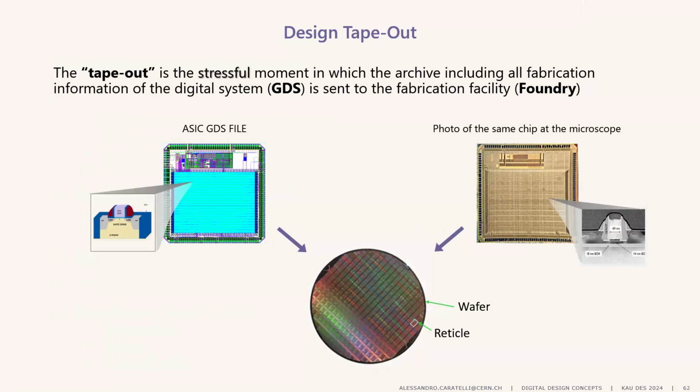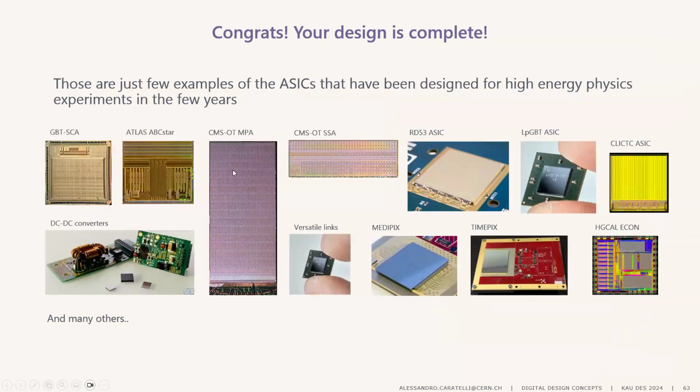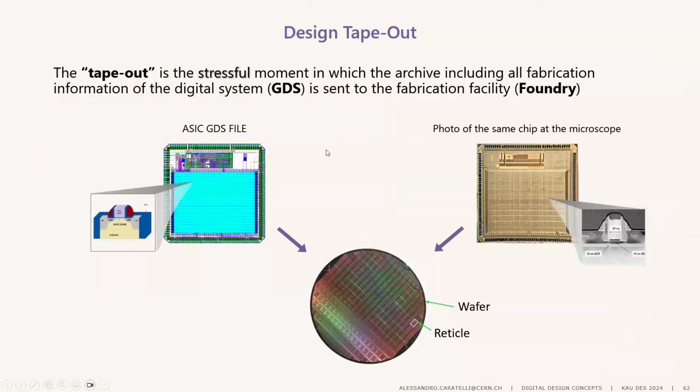Okay. We do extensive testing of the chips, and generally for large scale production, like for another project that I just finished, for this chip here and this chip here, we do what we call wafer probing. We prepared a testing algorithm that runs on an FPGA. Then we have a probe card, which is a lot of tiny needles that touch the top of the wafer even before cutting it. They touch the pads all around the chip and provide the electrical signal, so they can basically use the chip.